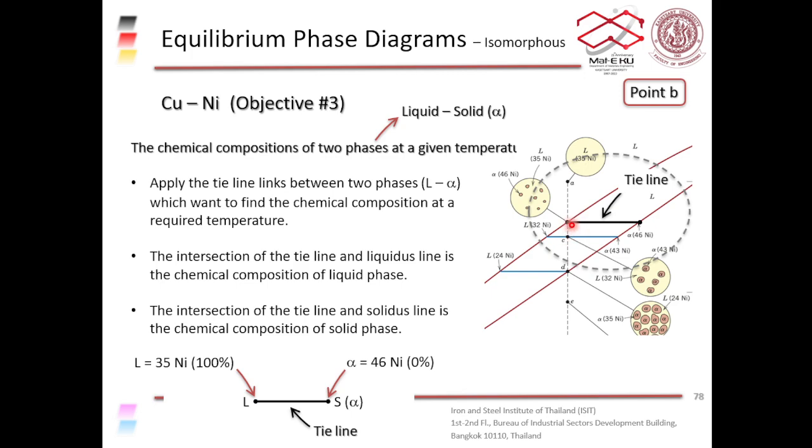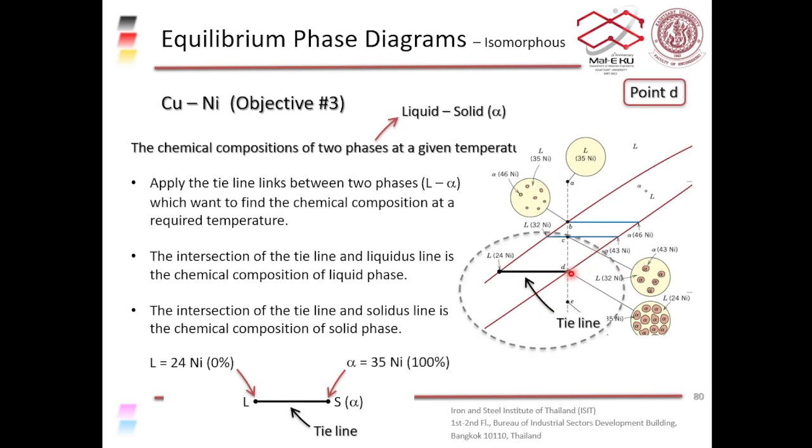And you see this tie line here, the right hand side of the tie line will get shorter and shorter as the temperature decreases, right? So in this picture, the right hand side takes up almost 100% of the tie line. In this tie line, the right hand side is almost 0. And we know that the fractional length of the tie line represents the different phases, right?